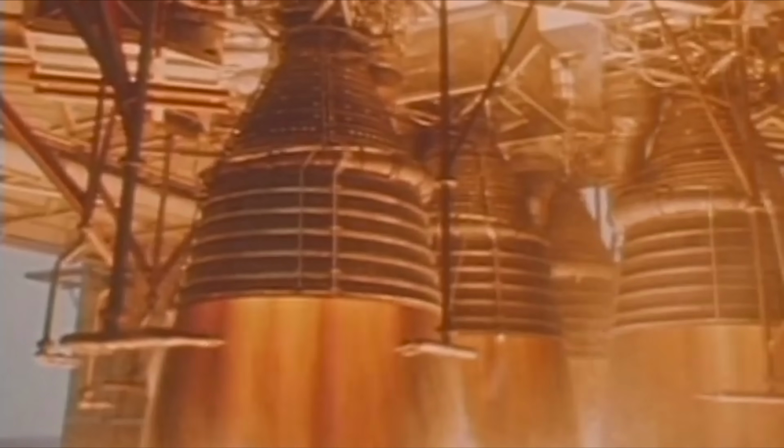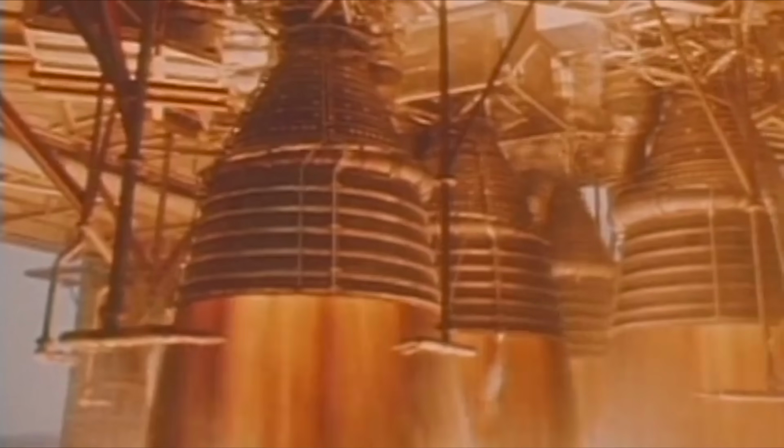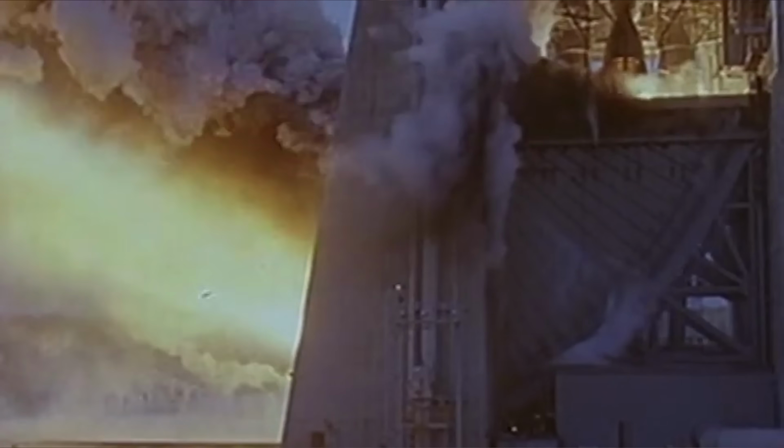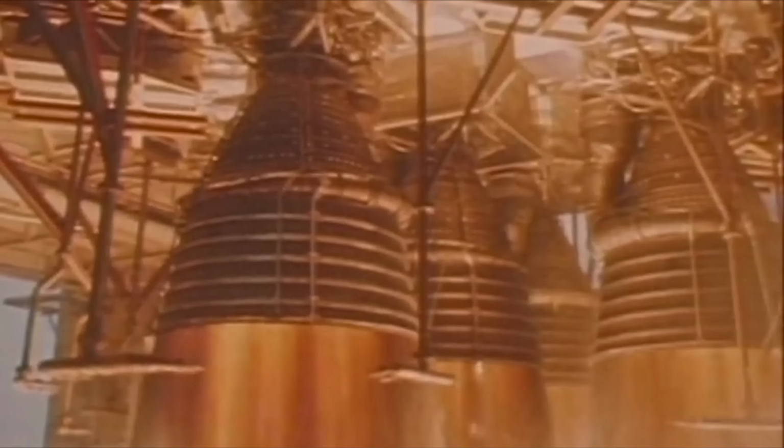This same situation is what limits the amount of available energy that can be used to spin the pumps. A bigger and more powerful engine needs more energy to run the pumps. And that same larger and more powerful engine doesn't actually heat up the same percentage of fuel flowing through it, so there is a limit to how powerful it can actually be.